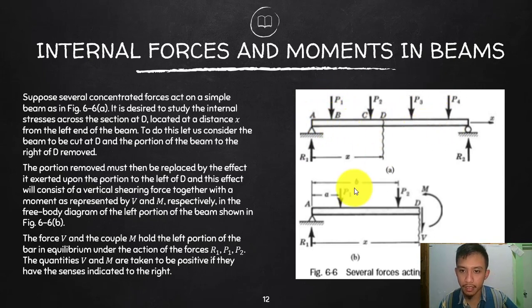the internal moments. So now for example, I want to investigate how much force or how much moment the beam is experiencing within this part of the beam, between the loads P2 and P3. Let's say I cut in this section, then I will be exposing what we call the internal forces and the internal moments. We will be expecting here a moment and then a vertical reaction,